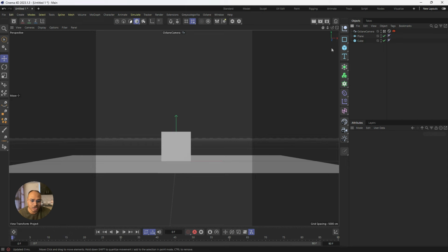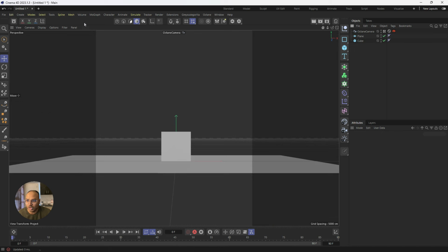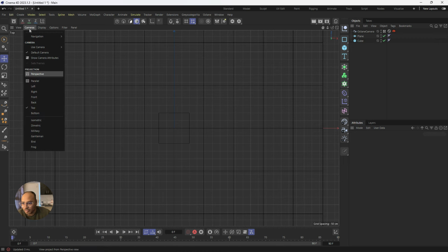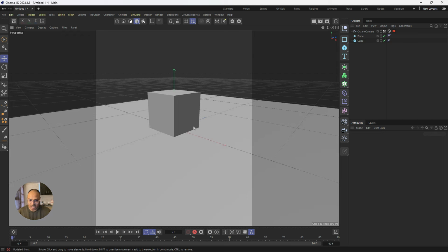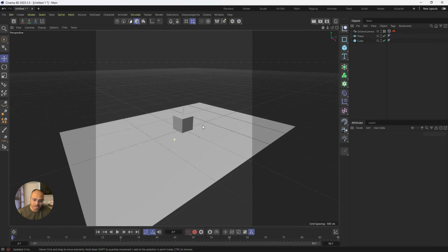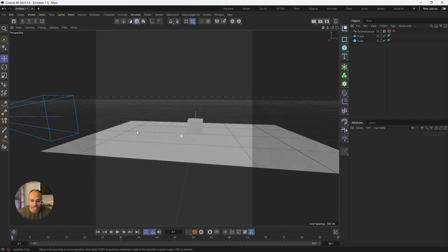Now I have already set up my camera. If I go out of my camera I can see that, but what I'm gonna do is open up this little window. It's gonna give me a 4 view kind of thing. Then I'm going to my second top window, click on this, and from here I'm going to change my mode from top to perspective, and I'm just clicking with my mouse and opening it like this. If I press F1 on my keyboard, I can go back to my camera, and if I press F2 I can go back to my scene, so I can revolve around here.